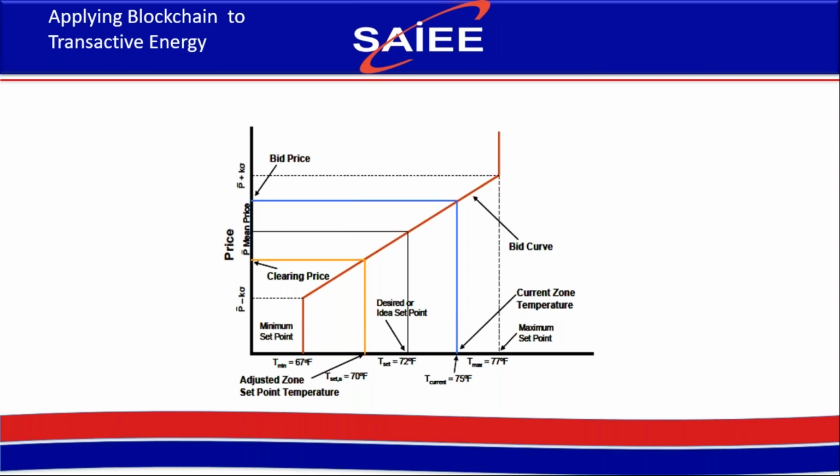You can call this pre-cooling. On the other side, heating is the same thing. If you want to get to a certain set point faster, you heat above that temperature. So here this HVAC system can decide to either buy or sell power.